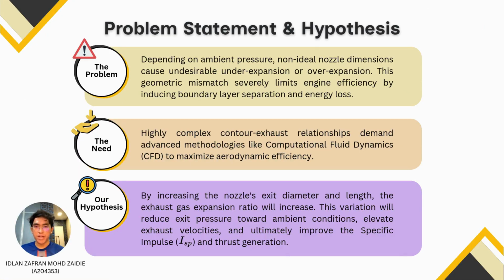The problem is, depending on ambient pressure, non-ideal nozzle dimensions cause undesirable underexpansion or overexpansion. This geometric mismatch severely limits engine efficiency by inducing boundary layer separation and energy loss. Because of these issues, highly complex contour-exhaust relationships demand advanced methodologies like computational fluid dynamics to maximize aerodynamic efficiency.